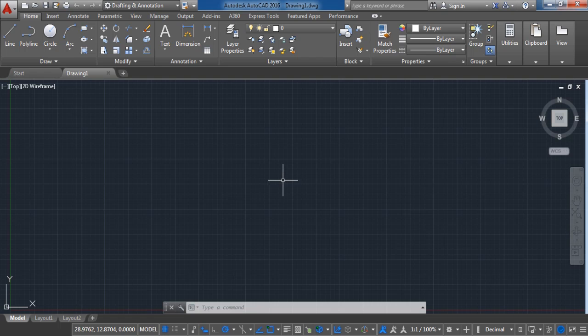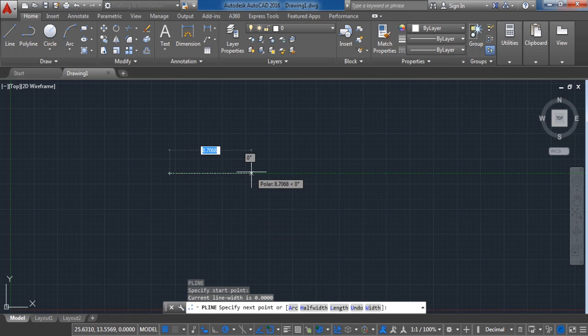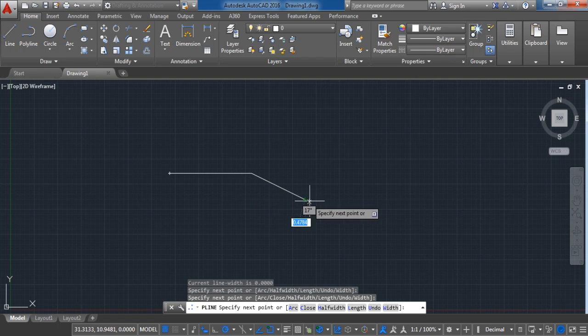You can find Polyline in the rebar menu next to line. You can write the short PL for the Polyline tool and press enter. With this tool you can draw just closed figures, so if you leave the figure open, you can edit it and it will cause some problems. Also, apart from straight lines, with Polyline you can draw circles and semicircles.